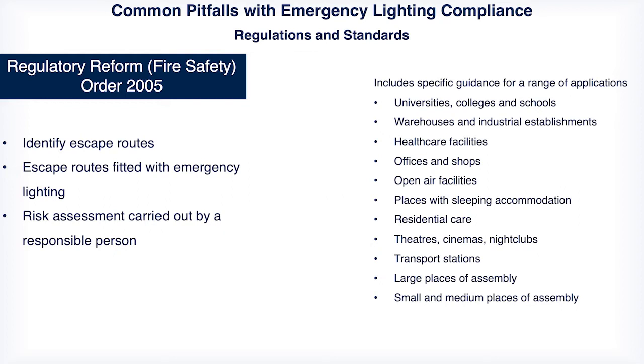And of course, there are also other requirements that health and safety people would talk about, which is that the findings are reviewed regularly, as are the rules and guidelines, particularly when there's any change of occupancy or change of use of the building. It's vital that the fire safety risk assessment is reviewed regularly.